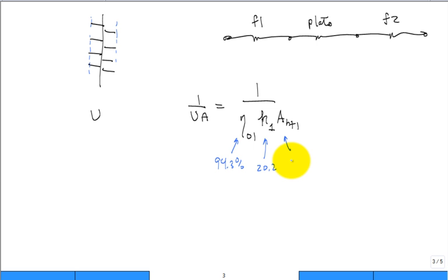So the whole heat exchanger has the area for heat transfer 695.3 foot squared. You come over here, I'll skip the plate for a minute, and we have 1 over the overall efficiency for the second surface, convection coefficient on the second surface, area for heat transfer for the second surface. Here are the numbers.